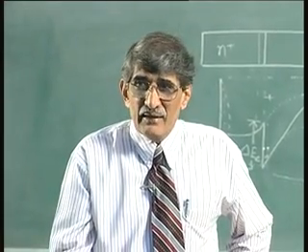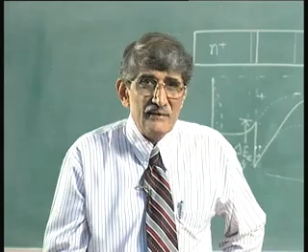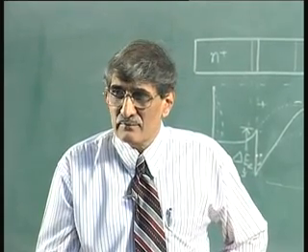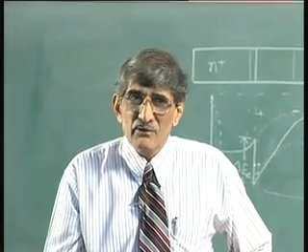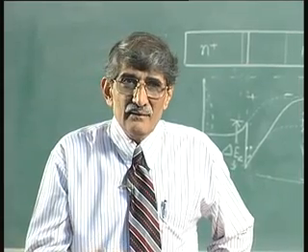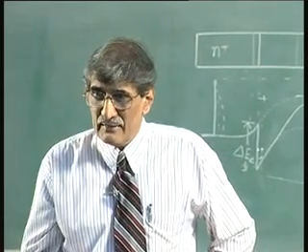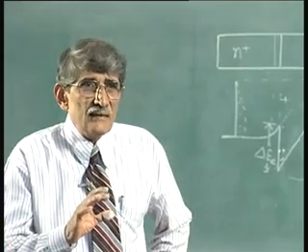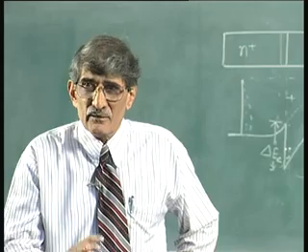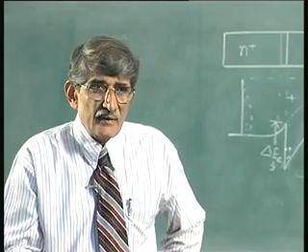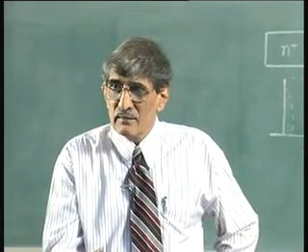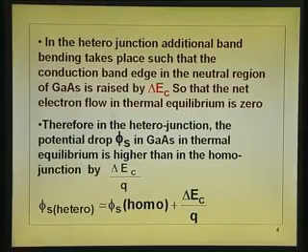Okay. Now, we have to see what will be the upper limitation. In fact, people never go beyond about 0.3, 0.35 mole fraction, because it introduces some trap levels and deteriorates the performance of the device. We will see that a little later, but right now we understand that we try to maximize delta E c, as permitted by technology and other criteria, so that the electron concentration in the unbiased condition is large. So, this is all what we have said now.